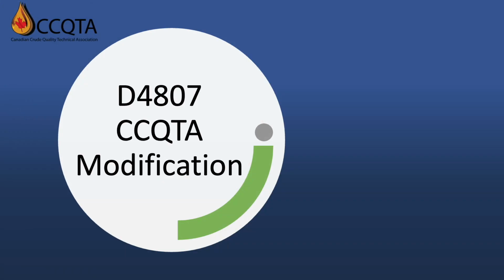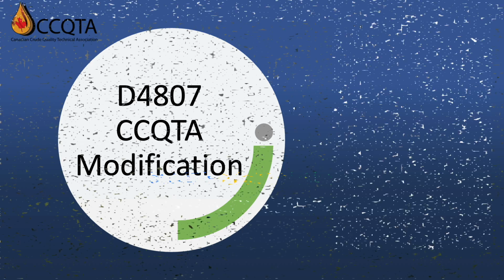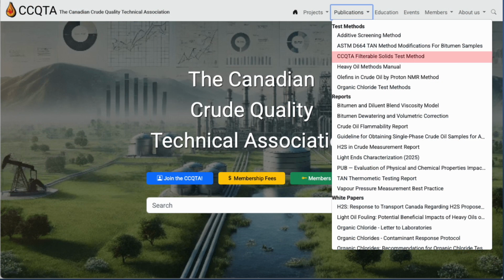As part of the CCQTA's work, and with the assistance of Bureau Veritas and Agate Laboratories, a modified version of D4807 was developed. This modified method allows for the quantitation of both toluene and water-insoluble solids, with the difference between the two being the water-soluble salts. The modified method also provides recommendations for additional testing that could be performed on recovered solids to provide further characterization. This method is available publicly on the CCQTA website under the Publications tab.